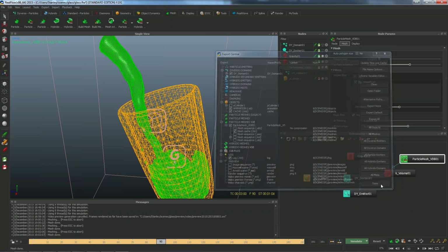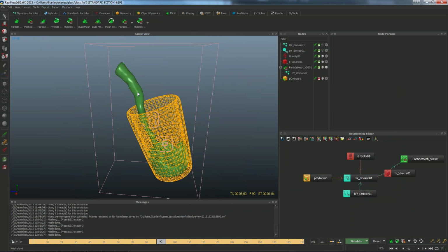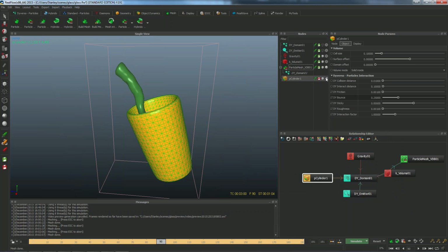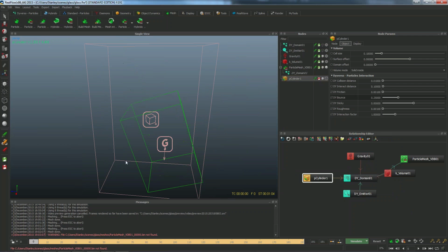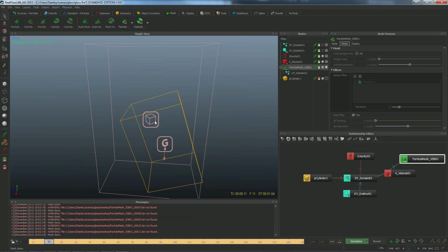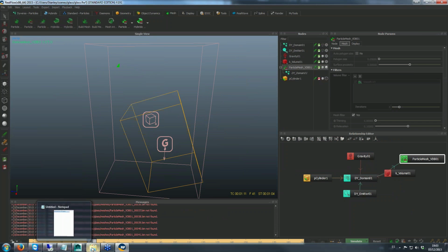So I just click as a binary, and let's assume that I'm pretty much done with this look of the fluid. Okay, I'm going to set up the glass as a bounding box actually, and here I just click on the mesh and automatically tell RealFlow to build up the whole timeline of meshes for me. So you see here that RealFlow is adding the meshes frame by frame.